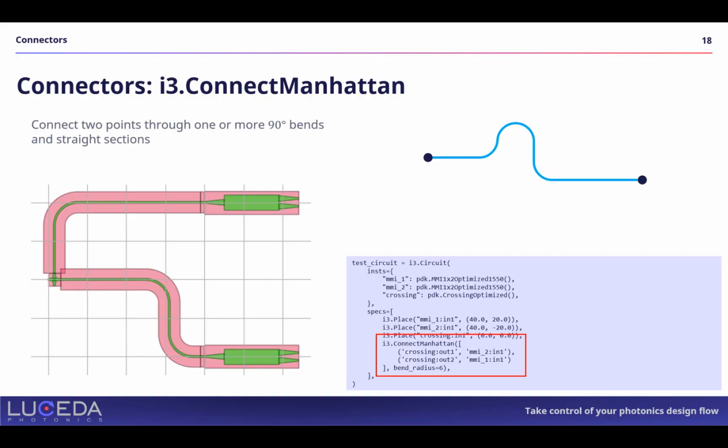Now we switch focus to connections. Once we have our instances aligned, we need to connect them. IPKISS allows for the easy implementation of connectors. Here we will see how to add arguments to this class to customize the waveguides, or use a new class, Connect Manhattan. If multiple connectors share the same properties, such as bend radius and rounding algorithm, then we can pass a list of the ports to create them together.